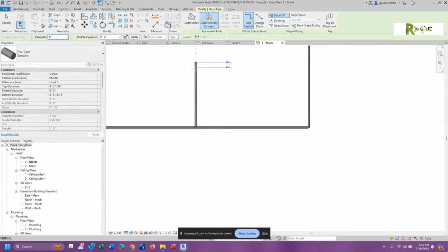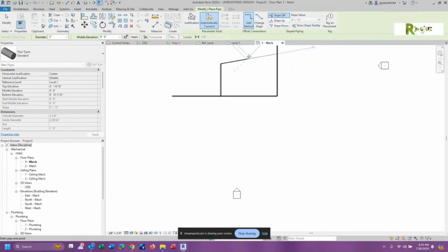Pretty cool. And if we go to draw to the right, but before we draw to the right, we say, oh, the pipe's going to get smaller here. So let's change the diameter to 3 inches. Go where the diameter is. That's it. You got it. Change that to 3. Watch what happens when you draw. It's going to put an elbow and a reducer, and yours is going to do a little bit crazier, put a little wacky elbow. But you see how it reduced the size of the pipe.